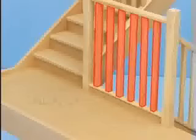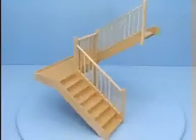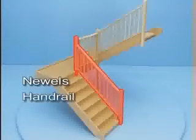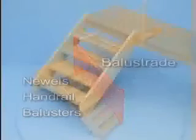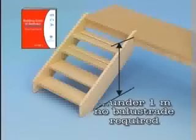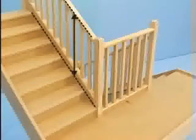The upright members between the handrail and the string are called balusters. The combined framework of newels, handrail and balusters forms the balustrade. The code states that if the height of a floor or landing is less than 1 metre, no balustrade is required. Over 1 metre, a barrier is needed and certain height requirements must be met.